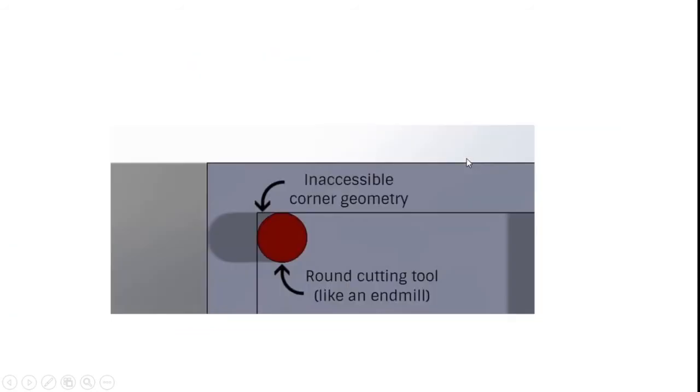What is the problem? Here, a circular end mill cutter is applied for making a pocket. When it touches the corner, the circular tool cannot enter the exact corner, so I cannot get 90-degree corners. Also, the tool moves and the tool paths are offset from each other. Two tool paths have their own straight lines, and the distance between the straight lines is uniform, but in the corners there will be an unmachined area. How can we avoid this unmachined area?